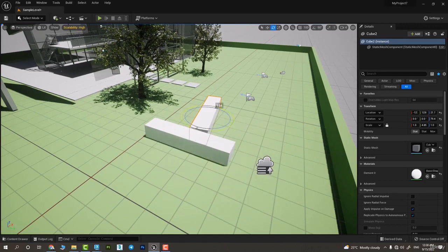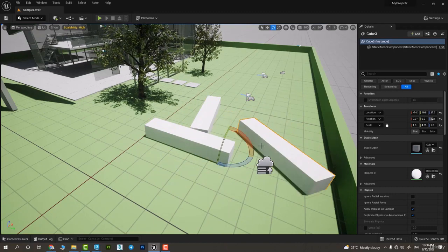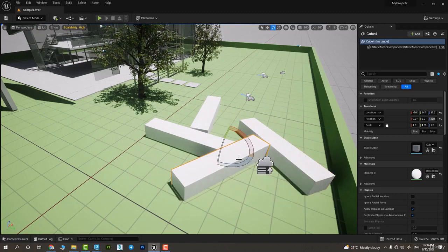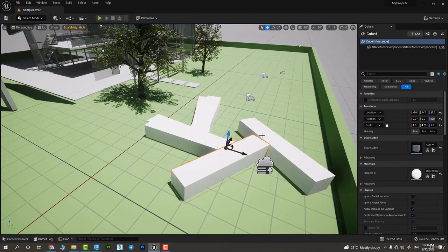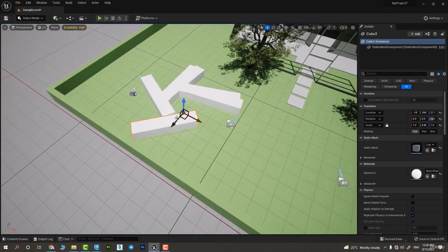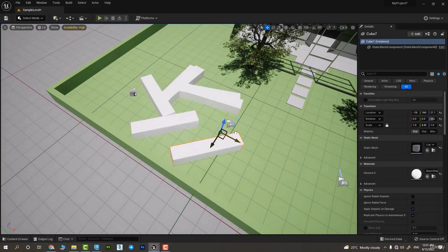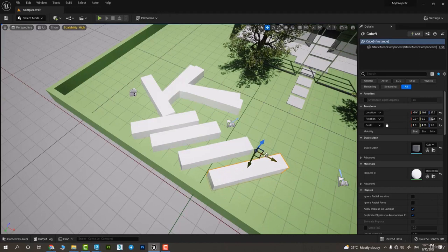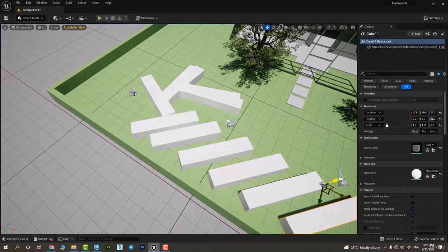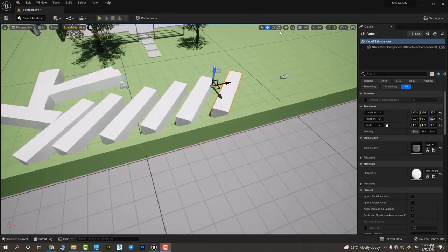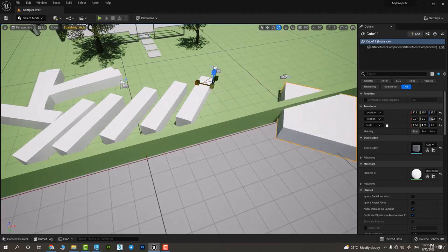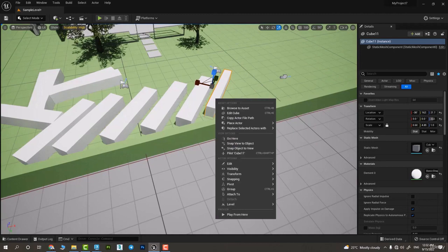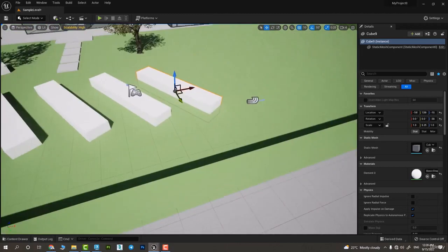All right, I'm gonna do the same thing. The trick is each time to just release the Alt key for a second and then press and hold it. So that's gonna be useful. I can do the same thing with the move button. See, I make new copies and move them instead of rotating them. And so those buttons that we learned about are very handy here. The only problem is that we cannot do the same thing with the scale. So holding down Alt key and making copies with the scale is not going to work like the two previous buttons.